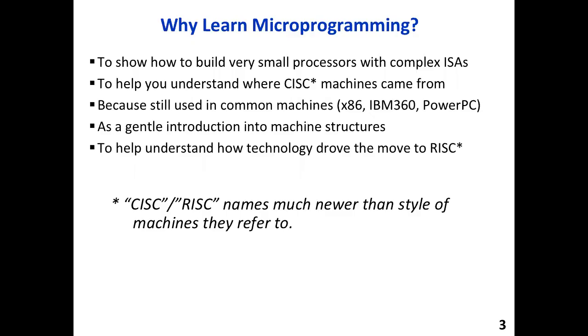What happens with microcode is you're trading off a little bit of space for flexibility. This enables you to change your instruction set architecture. So if you decide your CISC machine is better off with a different set of instructions than another one, you can design that instruction set specifically for that CISC machine hardware, and you do it by programming the microcode instructions.